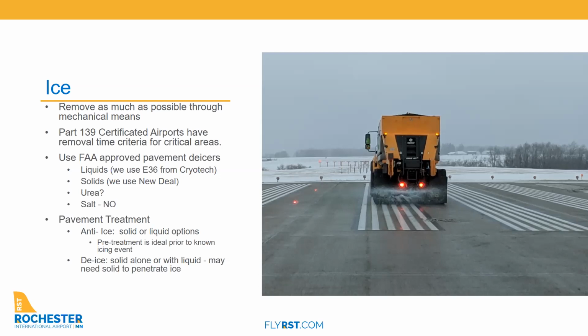And of course, most would realize that as you apply de-icer during a freezing rain event, if you can keep your chemical solution from getting diluted, it'll keep it from freezing. As you get more precip through, either rain or drizzle, you'll have to keep adding chemical to keep the solution strong enough that it won't allow that ice to form.